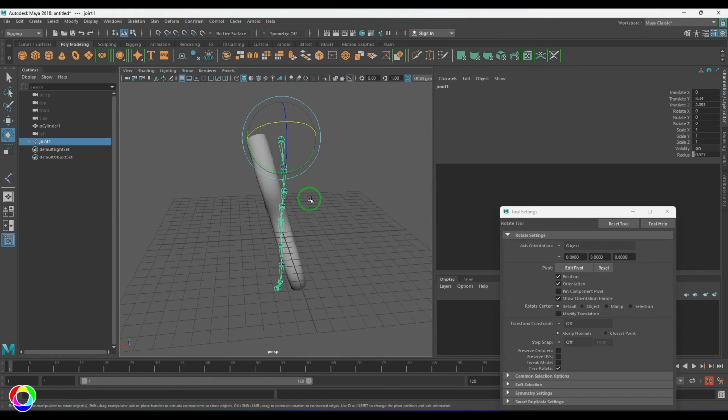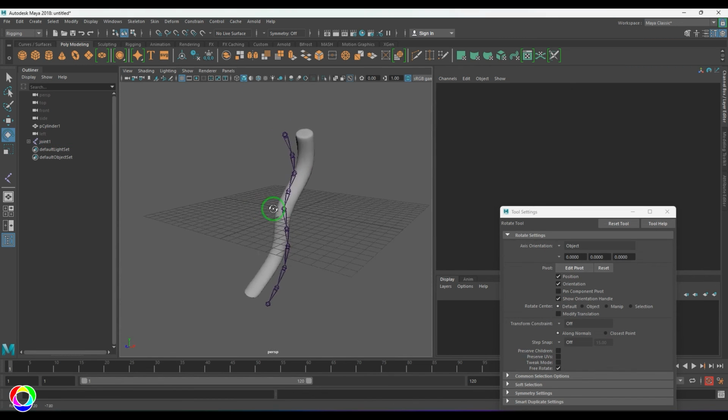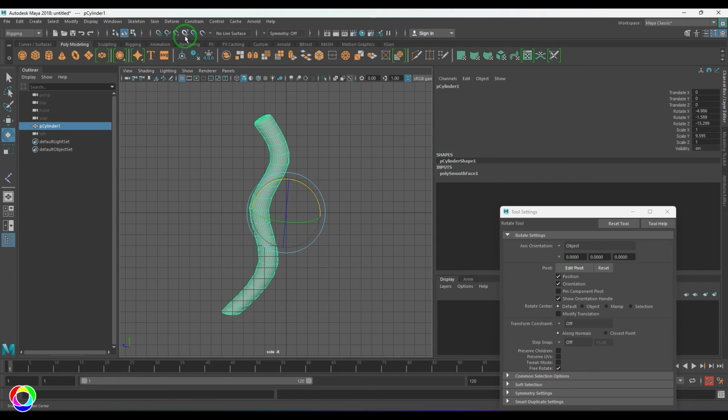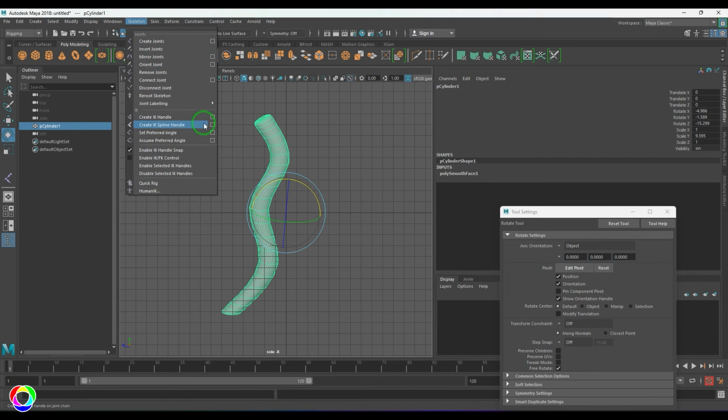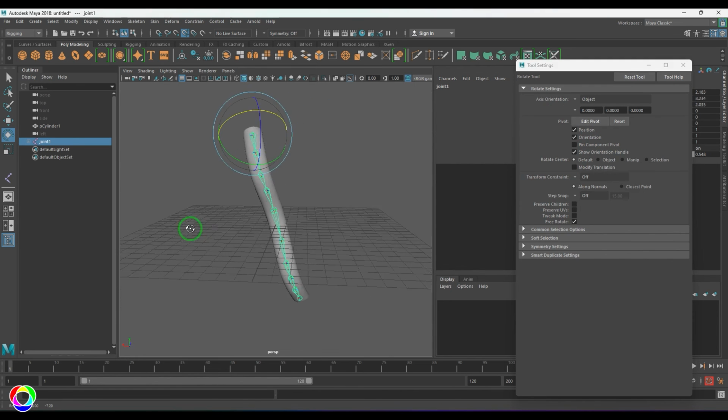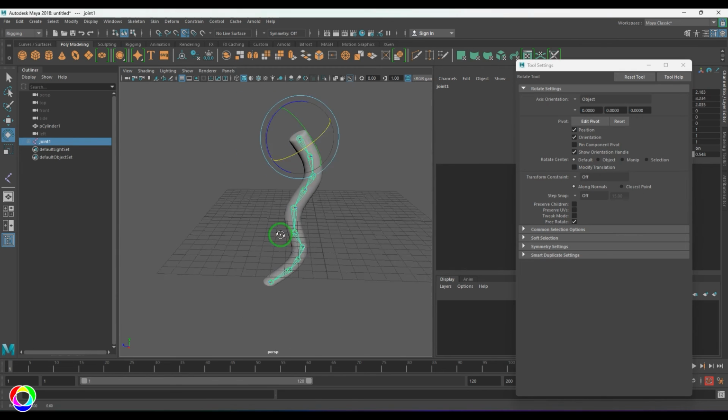And then when I just come to the perspective view, you should be able to see the joints are not really in the center. Now what you need to do is select this model and then enable this snap to projected center on. Then go to the create joints option. Okay, as projected centering is on here, now when I start placing joints, and then if I come here, you should be able to see the joints are perfectly sitting in this setup.